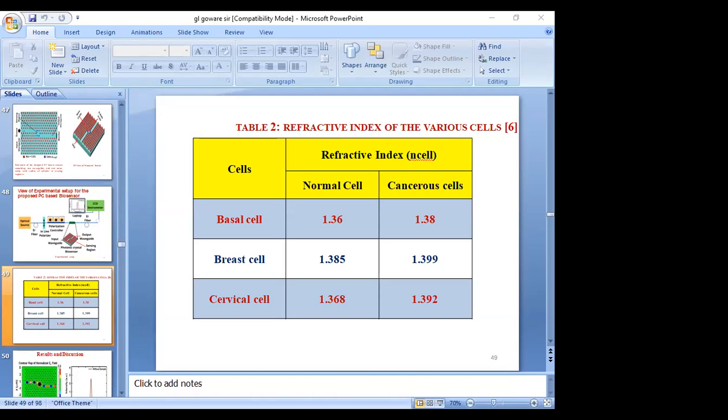Right. Bridge is best because a center tap transformer is not required. Otherwise we need a center tap transformer. Right. So what you can do, madam, is get a simple power supply made too. Because what I do with my students is I will not allow them to go anywhere. लैब में करेंगे, अगर रिजल्ट नहीं भी आते तो ठीक है, कोई प्रॉब्लम नहीं. Right. You design a 5 volt power supply, that is the basic requirement for any project. आप कौन सा भी करो, 5 volt सप्लाई चाहिए.